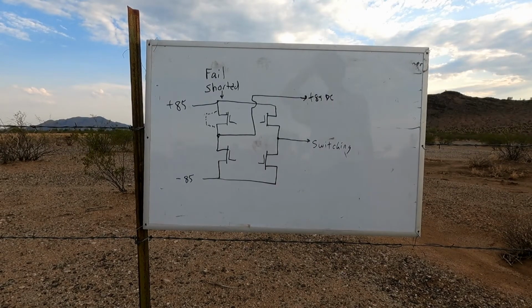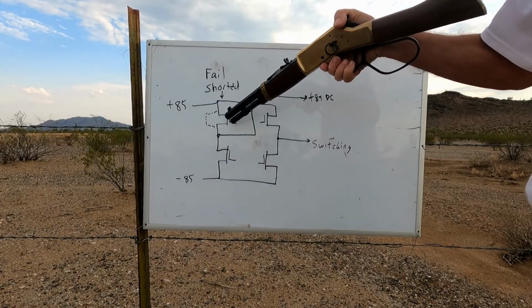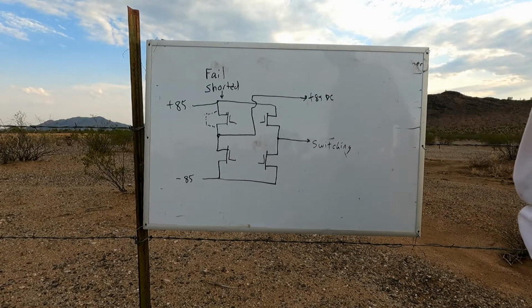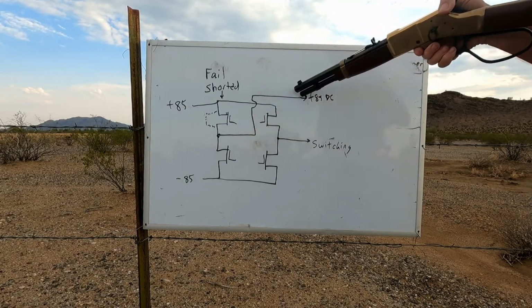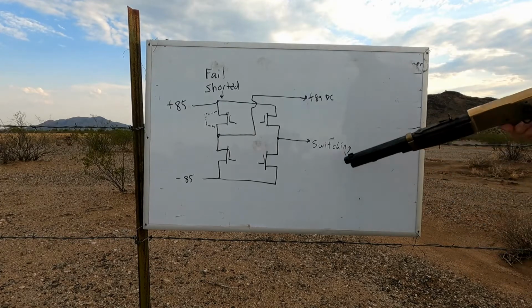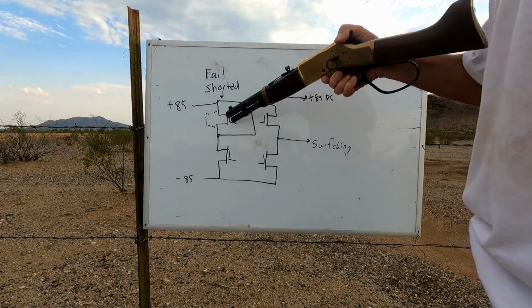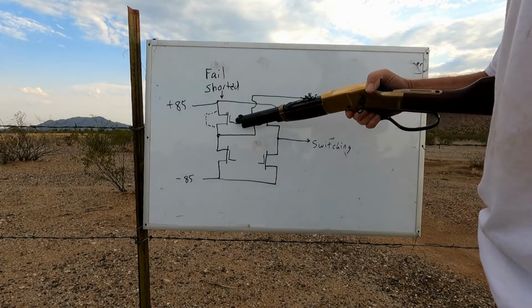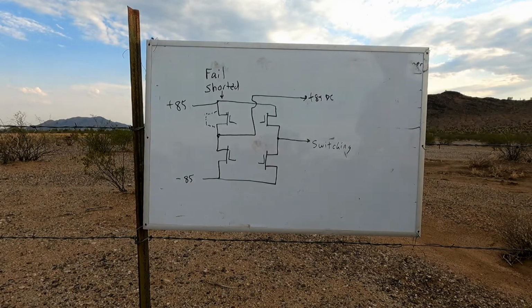So here's the issue with your transformerless output that's the most concerning. Let's say that one of the output transistors in your bridge circuit fails, and fails shorted, as can occur. It directly connects that plus 85 line to the output line that it's connected to. The remaining line may still be capable of switching, it may not. You can even have problems, not just a shorted device, but the control circuitry could have failures in such a way as to keep just one of these devices on constantly and giving an equivalent failure mode.